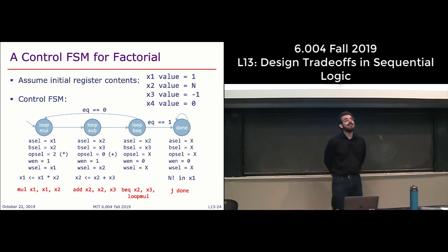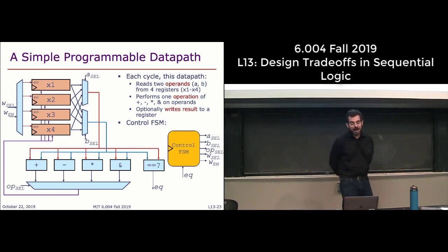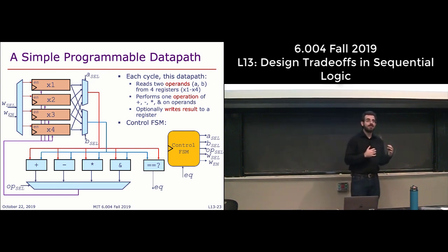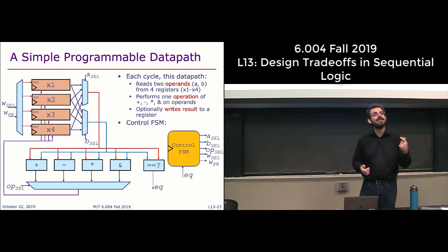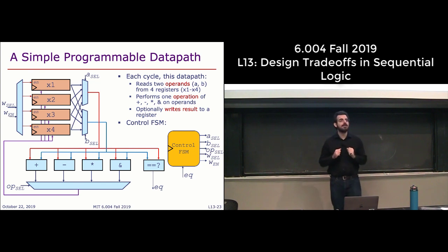And then the only step that we have left, at a very high level, is something like this, where we're going to have a few more registers, and so this is going to be a register file, and we're going to have a few more operations, and this is going to be the ALU that you already built in Lab 2. And then the other bit of crucial machinery that we need is a memory to give us instructions. So the key idea and the key difference between computers and FSMs is that your program is encoded in the memory itself, and you bring it from memory over time and then use it to drive the data path.